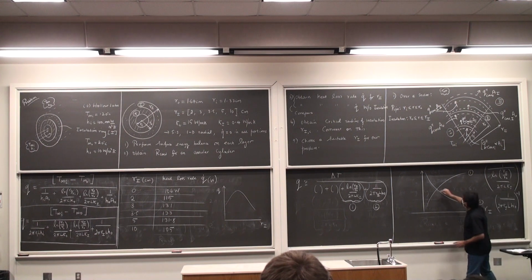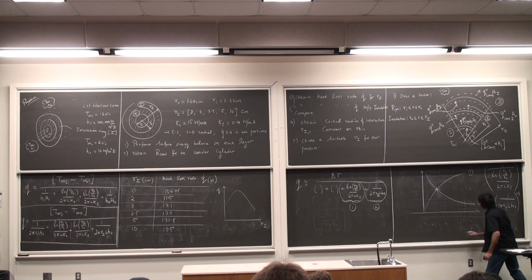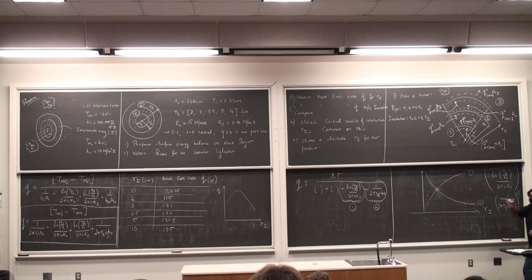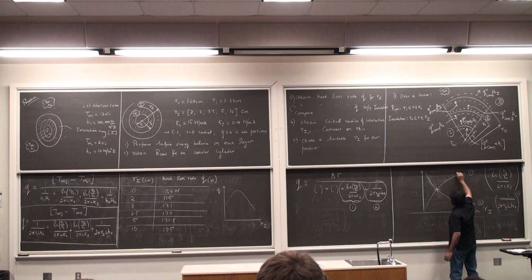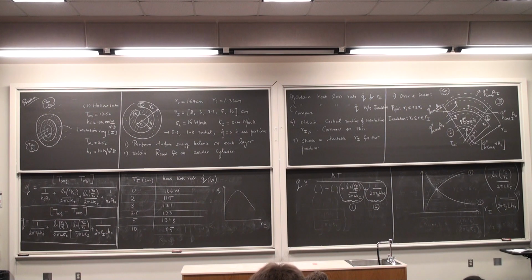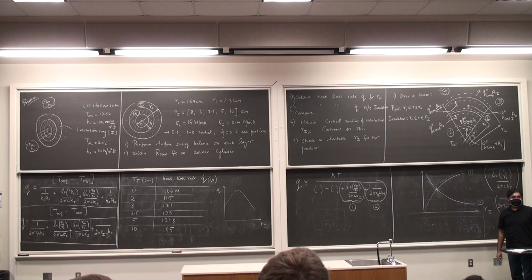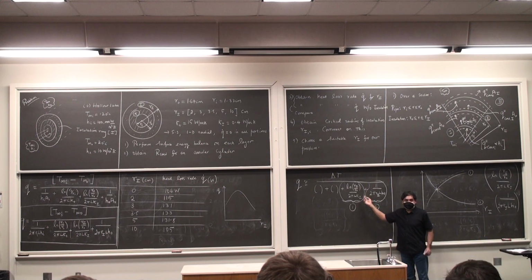So you see, I should point out this is not the inverse, this is just those particular terms. If you look at their behavior, you see that at a particular radius value, if I add these two profiles up, their effective behavior is something like that. So you see they reach a lowest point at some radius value, which means that at that particular radius value, my heat transfer rate is the highest. This is the combined behavior of those two dominant terms in this equation here.